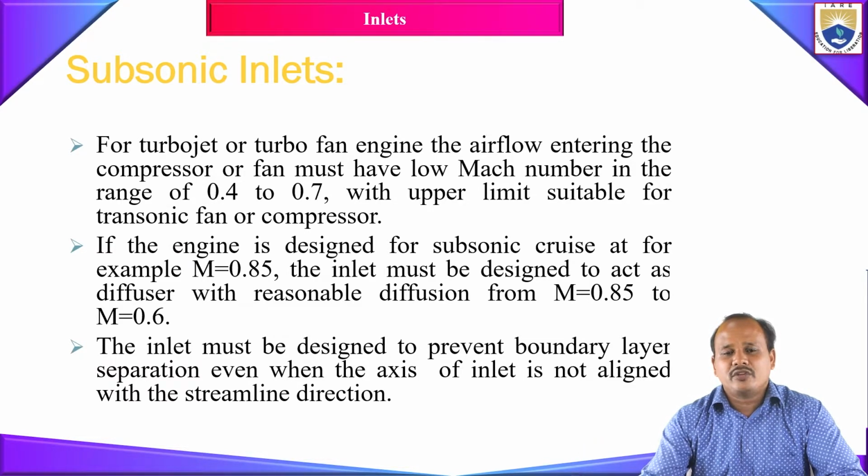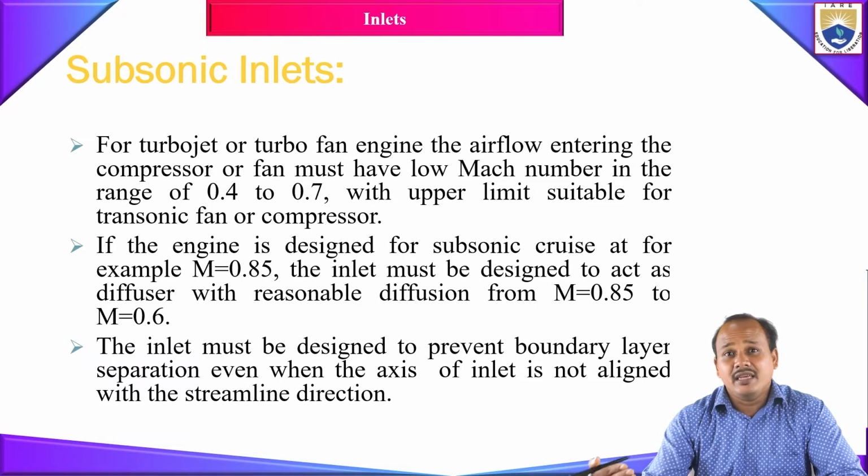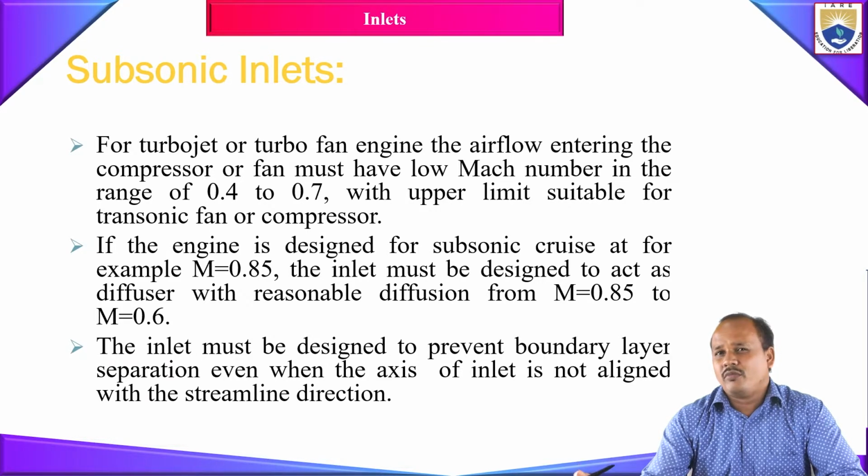In a supersonic flow, even a small disturbance will result in the formation of a shock wave. So you see how complicated your compressor is. If a shock wave forms, the process across the shock wave is non-isentropic. A huge amount of loss will happen. Including your aerodynamic loss, if there is a shock formation, a further increase in the total pressure loss will happen.